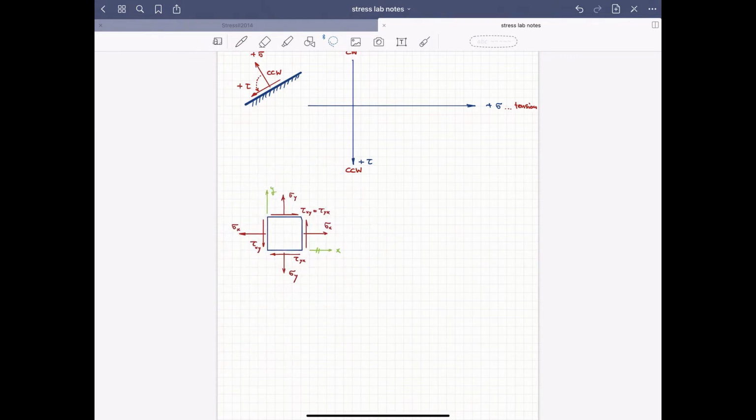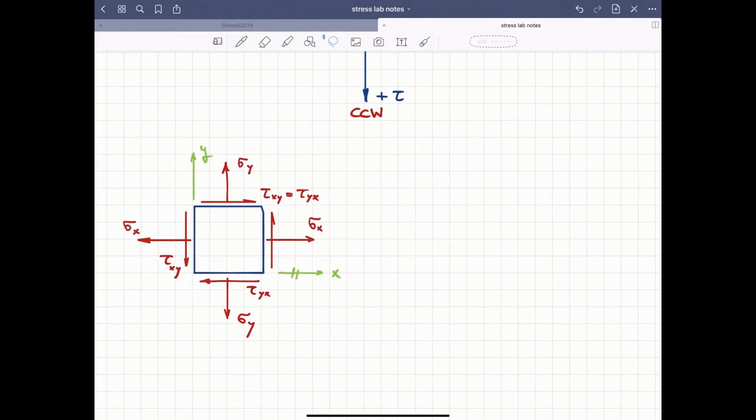Next, I pick our stress block and try to see how a stress block fits into that picture of Mohr's circle. First, note that a stress block has 4 faces. So Mohr's circle draws 1 point per face, and I simply start with the first face. That's the one perpendicular to X, the positive face, and I want to draw the stresses that we have using the sign convention from our stress block. So I see sigma x and tau xy.